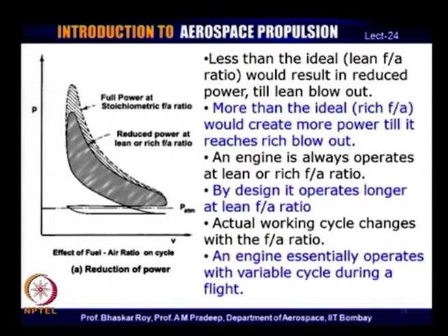which means the engine could be operating under a lean fuel air ratio or a rich fuel air ratio. If it is too lean, it could have a lean blowout. If it is too rich, it could have a rich blowout. So, that is the danger which I was talking about, and you will have no work done out of this cycle.